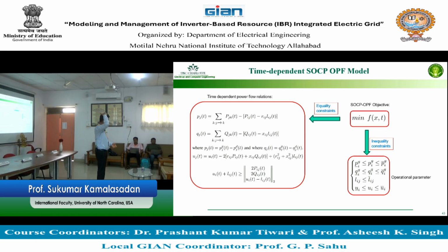Remember, net load positive or net load negative. So you collect that information of the variation of DER and the variation of the load. Not difficult to visualize, right? You get that information and then you run the power flow. Is there anything else I need to run the power flow continuously from the field other than the node and the DERs? What do you think?